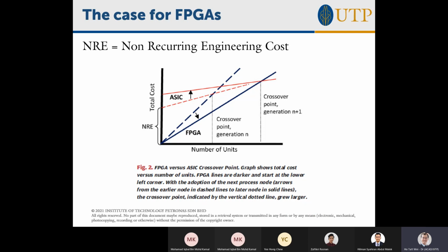Whereas for a microprocessor, if you want to do an AND, you actually have to have an instruction fetch, decode, ALU, and maybe you store the value back into your register or into your memory. You need all the stages of that pipeline. So for sure, an FPGA, if you custom program it, or an ASIC, is going to be faster than a microprocessor, because a microprocessor or microcontroller has a fixed number of computation cycles, since it's general purpose. So this is the reason why we're going for FPGAs.